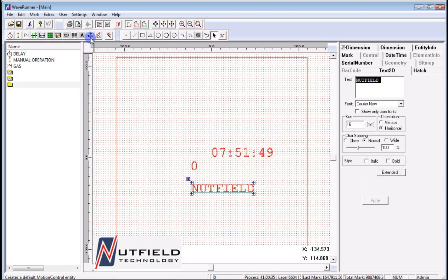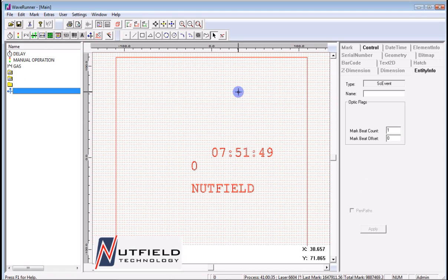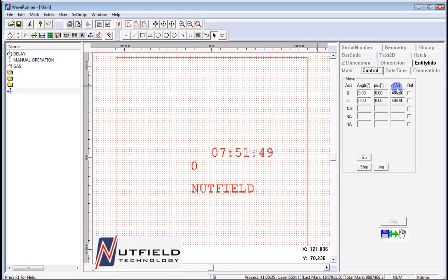Motion control is only available if motion control is activated. It allows the user to program in absolute or relative moves within the job flow. For example, to move the focusing axis a fixed distance when a part to be marked has two distinct marking planes, or to execute a homing event. Motion control is covered in a separate group of lessons.